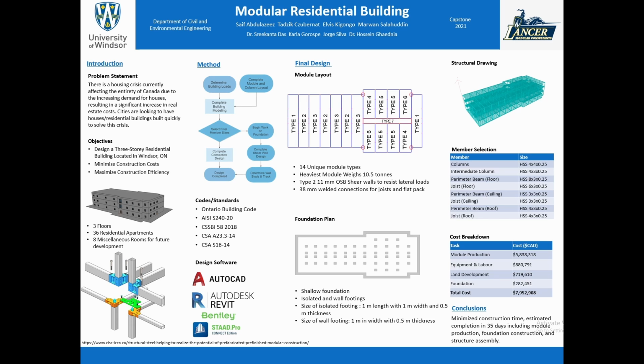An important aspect when talking about modular construction is its standardized vector block connection. In the diagram shown in the bottom left corner, the upper vector block of the lower module, highlighted in orange, is connected to the lower vector block of the upper module, highlighted in blue, with 2 tension bolts. In between them lies a gusset plate, highlighted in green, which is used to connect and transfer the load and shear between 2 adjacent modules. A 90-degree connection is generally the typical connection used, but in certain cases, such as the ones circled in red, a 180-degree connection is utilized.